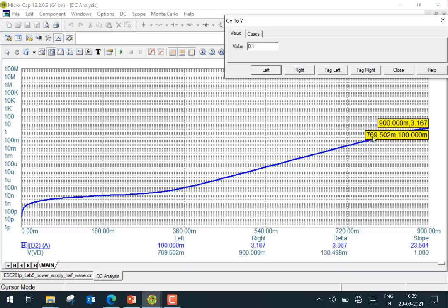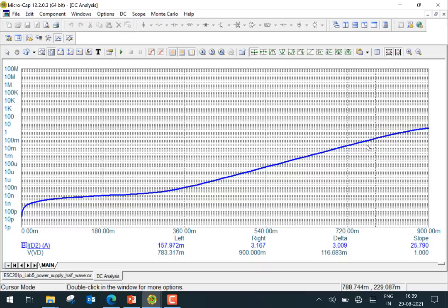It's not too far from it here, because we can see points, it's only 0.77. But when we were making a power supply, we were getting a diode drop of, it appeared, because we had used 5.7 as the transformer output, and we were getting 4.8, so almost a 0.9 volt drop here, right? And if we go back, so let's close this. If we look at 0.9 volt drop here, 0.9 volt drop is requiring a current of 3 amperes here, right?